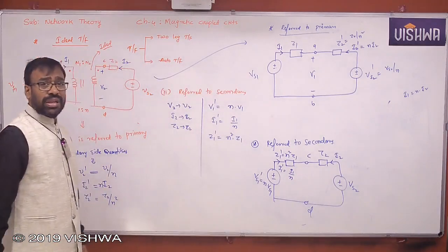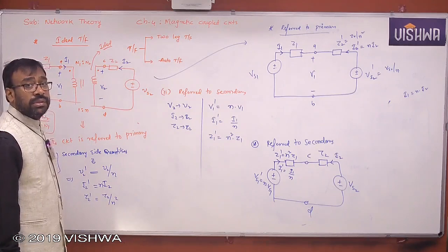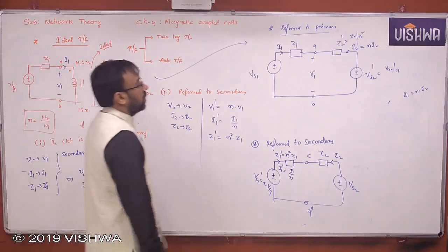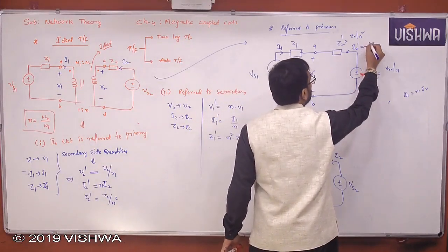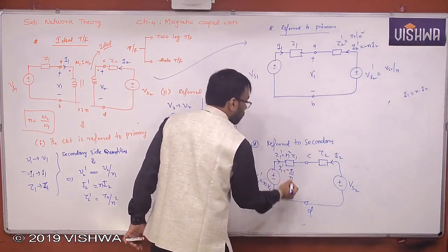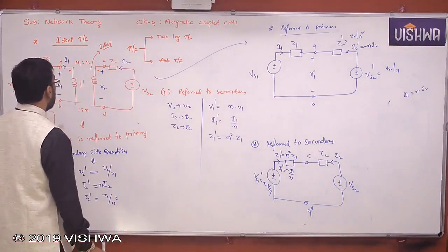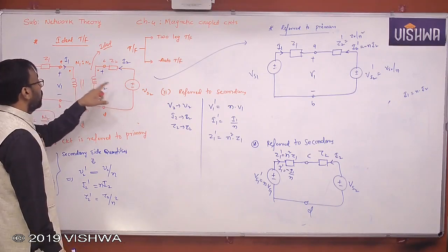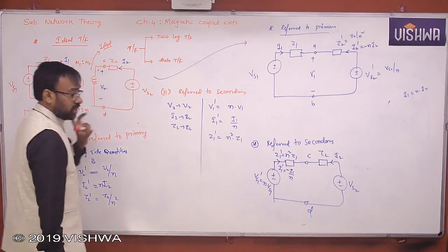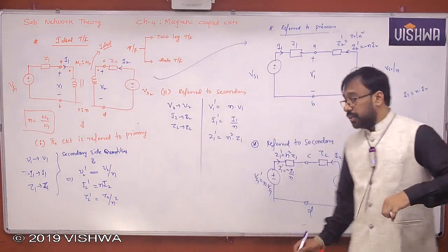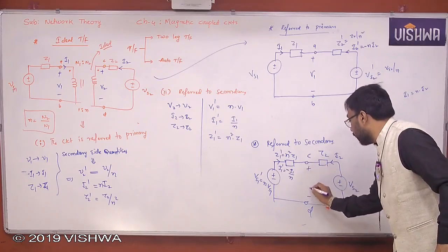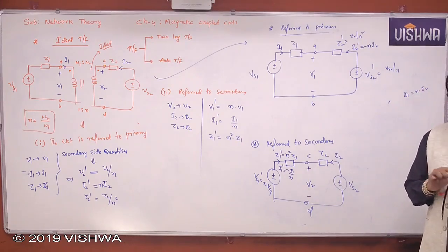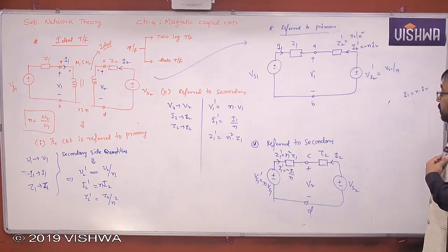But positive sign or negative sign, how do you take it? Entering, it's supposed to be leaving, right? Therefore, it is minus. It is also minus. There is no problem with voltages, yes or no? Because positive, positive entering, and here dot plus minus, here dot plus minus. There is no problem at all. So please note down. This is actually C and D. You are getting V2. So this is how ideal transformer problems can be handled. We'll see the remaining things in the next session.